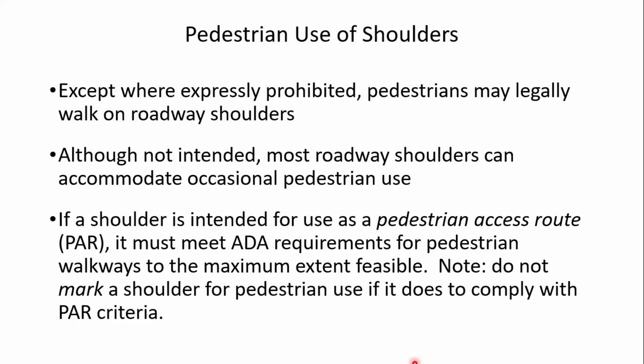I would note, though, that if a shoulder is intended for use as a pedestrian access route, the PAR under PROWAG, then it must meet the ADA requirements for pedestrian walkways to the maximum extent feasible. But notice this is an exception rather than the rule.